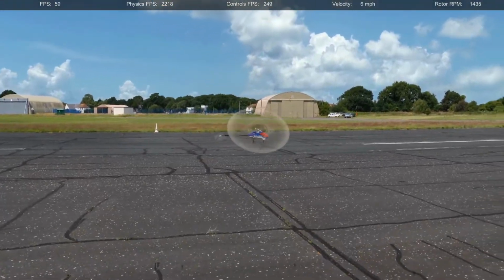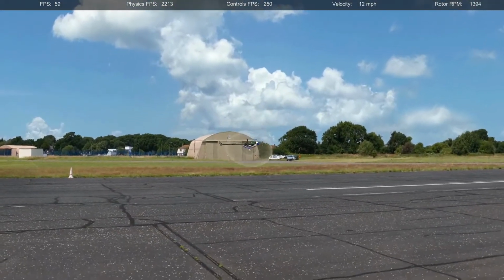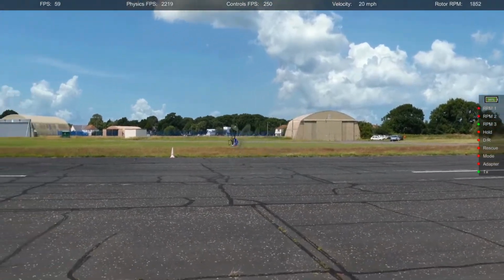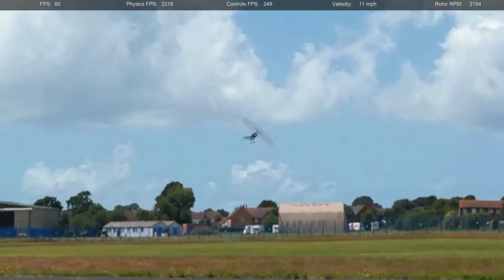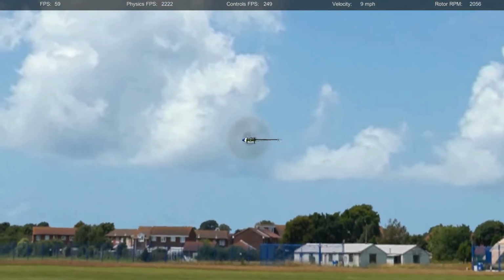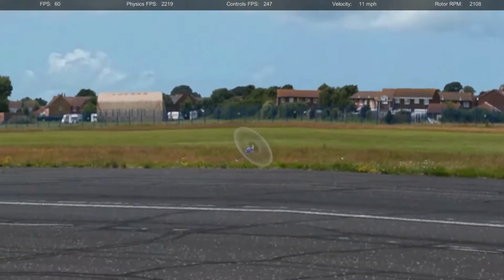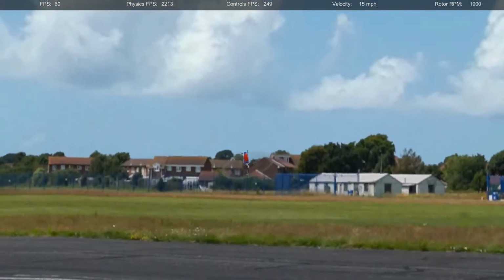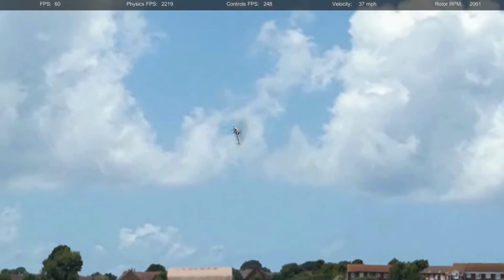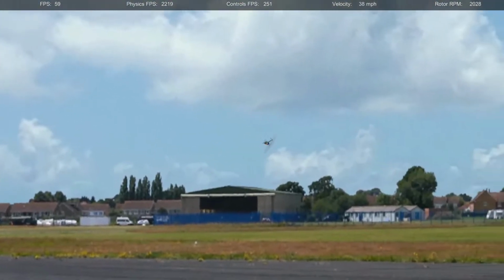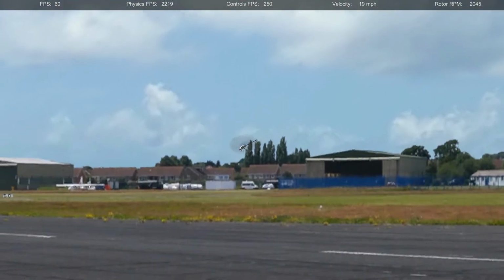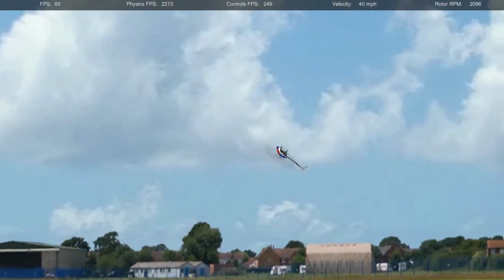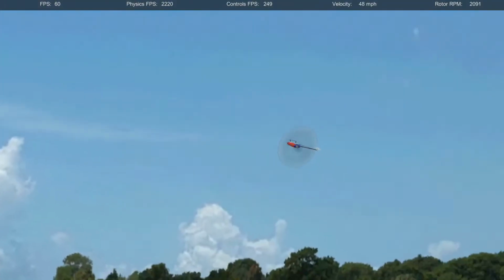So this is the airplane we're flying right now. We had a fiber optic shape sensing system, and you can see the fiber optics in the lower right. We also put pressure caps in the airplane, and one of the things we came up with is a little tiny box. It's about a foot long, maybe 6 inches wide and about 4 inches thick, and it measures 100 pressure ports at a time. It weighs 2 pounds, by the way.